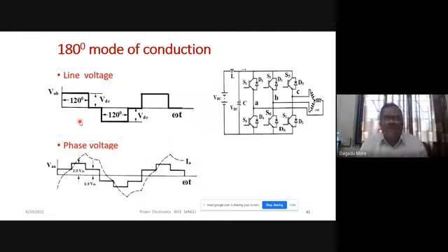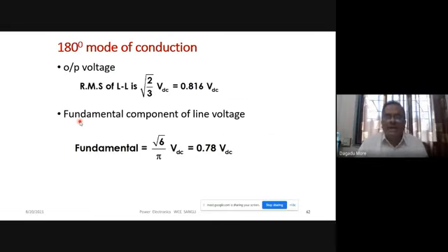This waveform is similar to our diode bridge source current. And what is the THD content of this particular waveform? Can you just point out the THD of this waveform? 31.92%. 31% around. Okay, so we have already done it, and now here we have shown it.